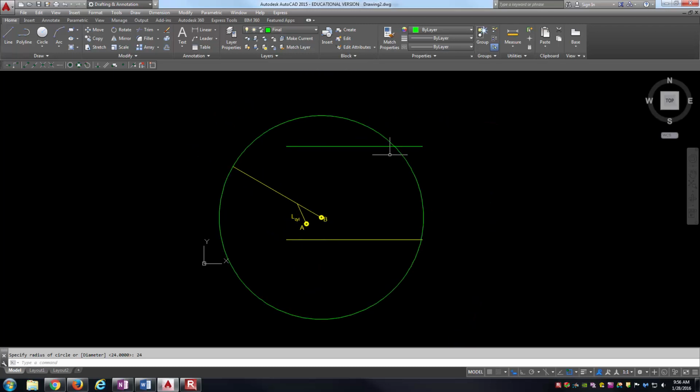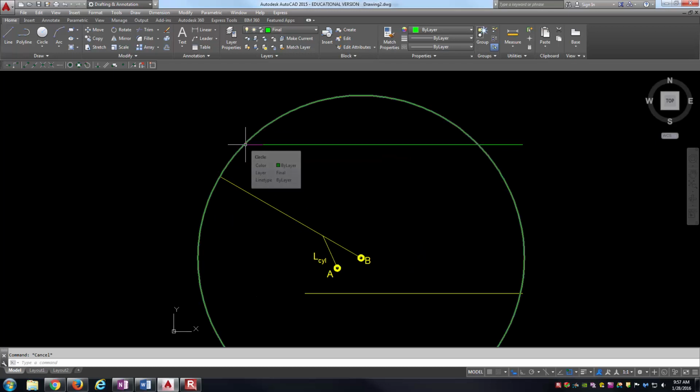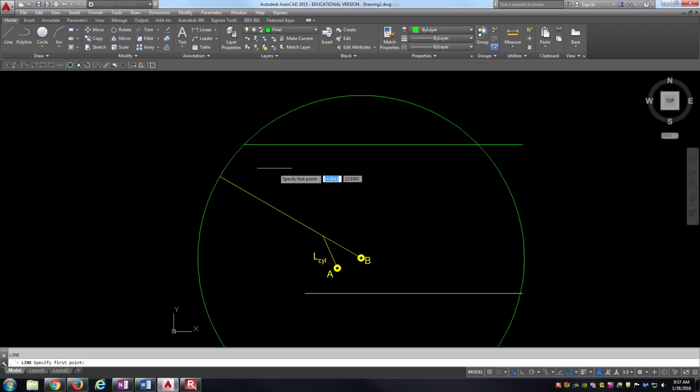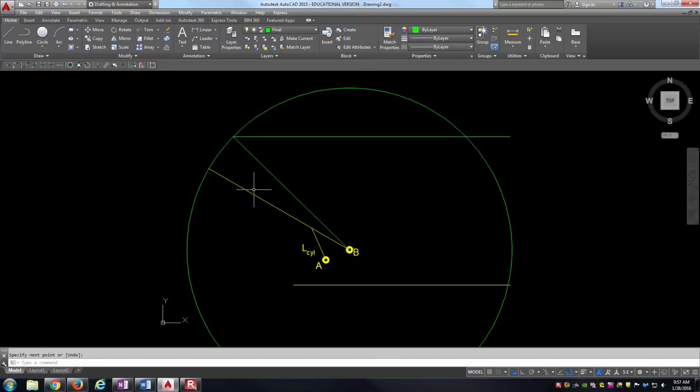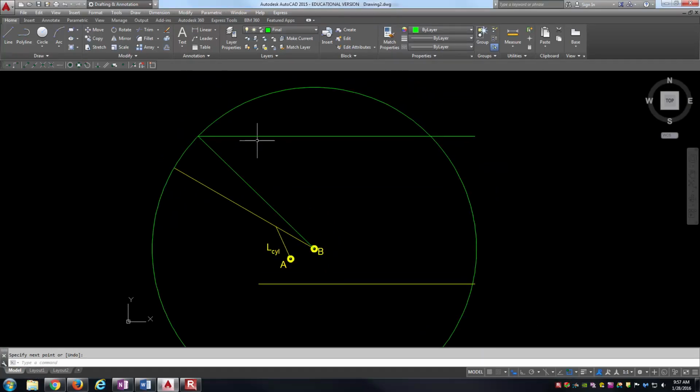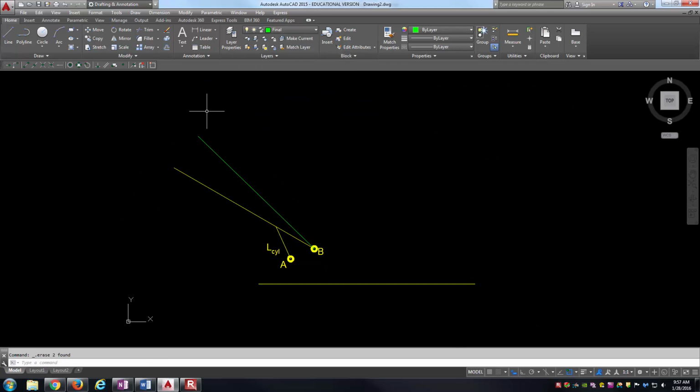And so notice we've got an intersection point over here. Really I'm interested in the intersection point over here to the left. Again, it's a method where we're going to have to extend, so I'll type in extend, select the boundary, hit spacebar, select the object there that I want to grow, and have it extend over. And so this point right here represents point D after it moves this arc length up to 22 feet. And so here I'll just get a line tool drawn in here in order to represent that link BCD there. And so at this point I can remove both of those pieces for construction.